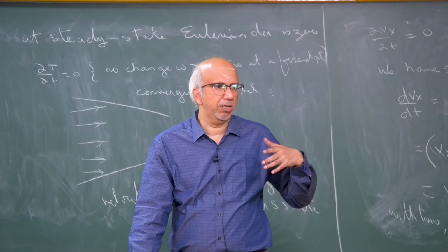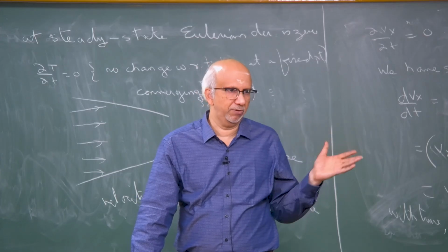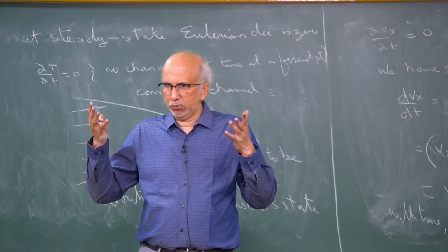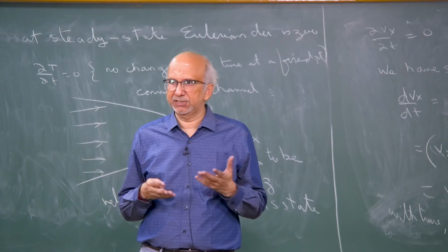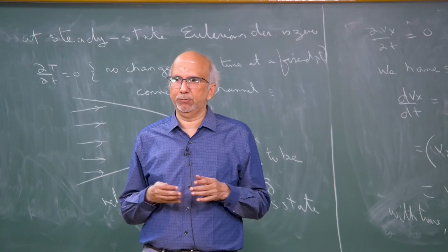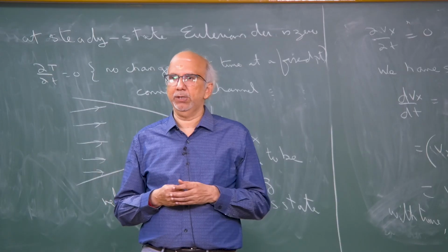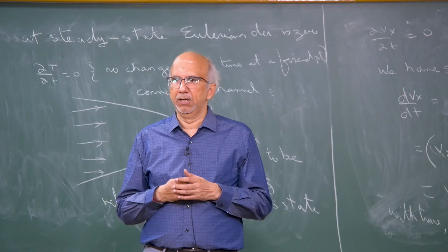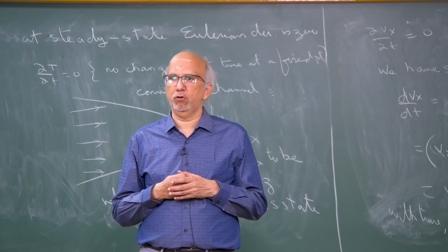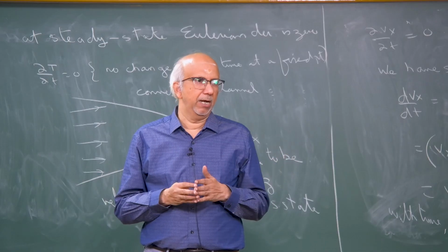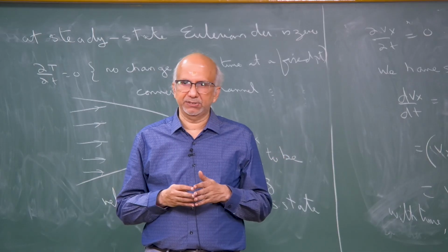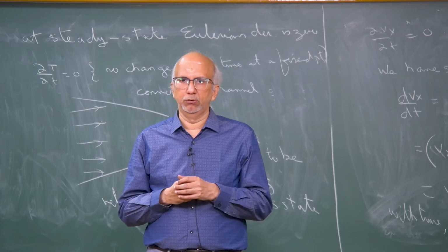And how do we extend whatever this idea is, because whether you are talking about Lagrangian or Eulerian approach, this relationship between the Eulerian approach and the Lagrangian approach, we want to extend it to a larger region in terms of control volume and control mass, because tomorrow I may be doing a mass balance or an energy balance around a control volume.